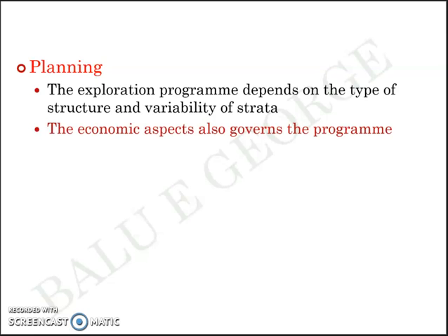The economic aspects also govern the program, which means there's a limitation for the funds which can be earmarked for the site exploration and also the foundation. Let's take an example. If you're designing a house or residential building with, let's say, a total cost of 60 lakh, in such a case you don't have the luxury of spending about 10 lakhs on the substructure.